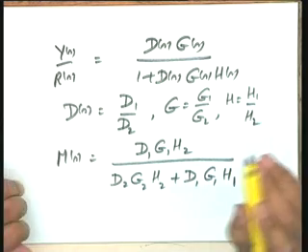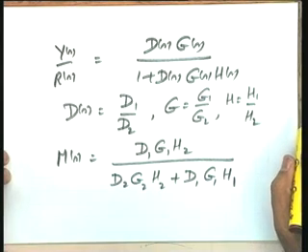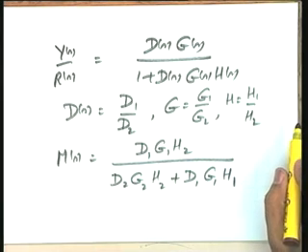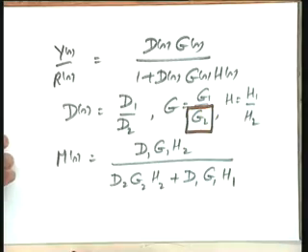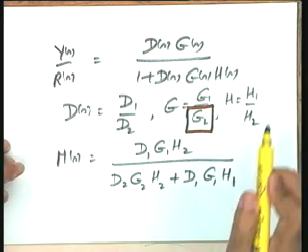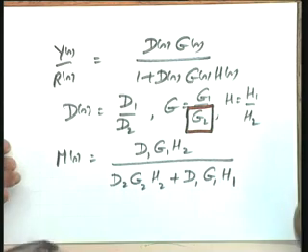Fine. Now please see, if you want to shape the dynamic response, it means you want to make it different from the open loop response, and the open loop dynamics is guided by G2, because G2 is going to give you the poles of G. So it means the pole locations of G2 are not acceptable to you.